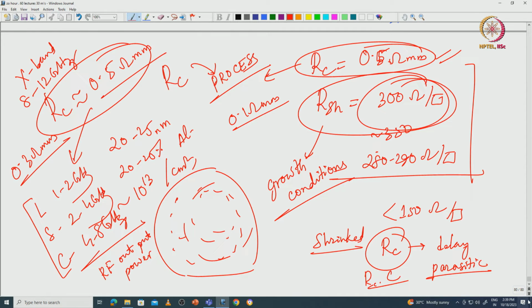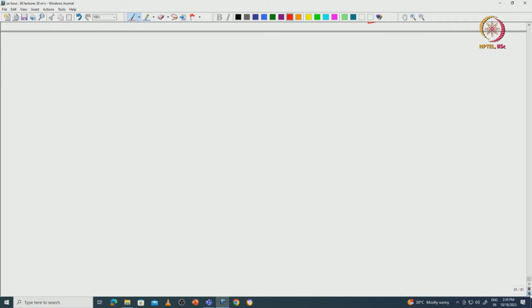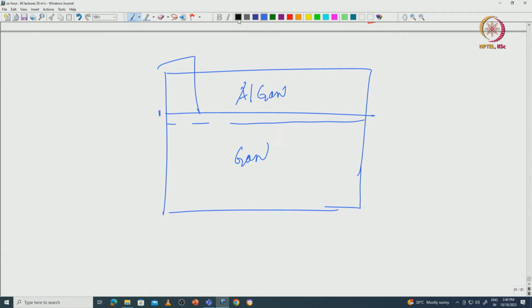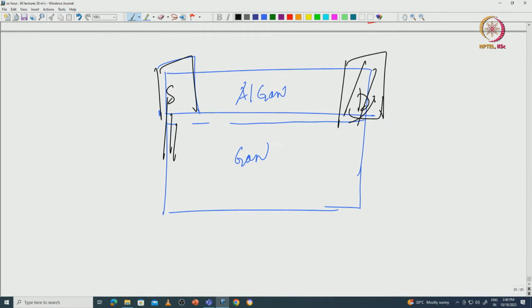Okay. All right. So we talked about the contact resistance in brief, and we talked about the device geometry in general. That's a 2-finger device. That's a single finger device, by the way. And so, okay, this is AlGaN again. This is GaN. As I said, this is how you form the source and drain. You isolate the device, of course. This is annealed, so the metal spikes down, and the 2D electron gas is here. Then you have a gate here.